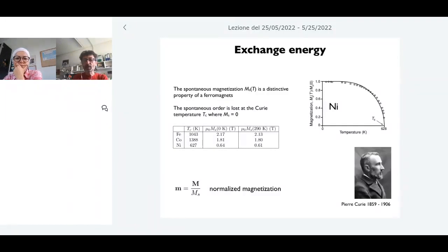The spins at the atomic level are already aligned in a certain direction, so that if you isolate a small volume of your ferromagnetic material and look at the magnetization, let's call it spontaneous magnetization, at a certain temperature that value is fixed. The orientation of the magnetization could change, but the amplitude is always the same.